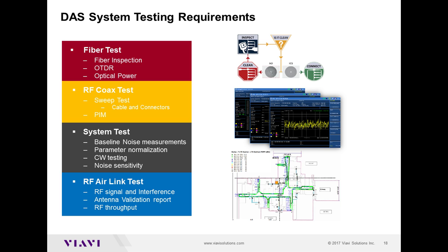So your inspection has to be done, and then you will measure. Basically, you will transmit a certain power level, and by using a power check or some solution like that, you can measure the loss, and then you will write it on your spreadsheet that will be provided as part of the design document. Remember, before you start working from the design document, you will have complete specs of how all the radios and everything is laid out in that venue. It will also provide you with a list of each and every radio, each and every cable that is there, so that you can write down what the losses you are measuring.